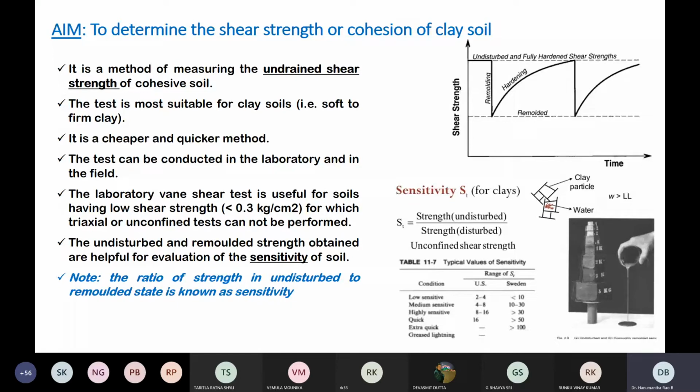See, this soft clay has a high friction. So when you are trying to grab a soil sample, say from the 10-meter depth, if it is too soft, it will easily slip. We never could grab any kind of soil clay sample, especially if it is a soft clay, from larger depths. So in those situations, the Vane shear is the most ideal test to determine the shear strength of the soil. So these are the situations.